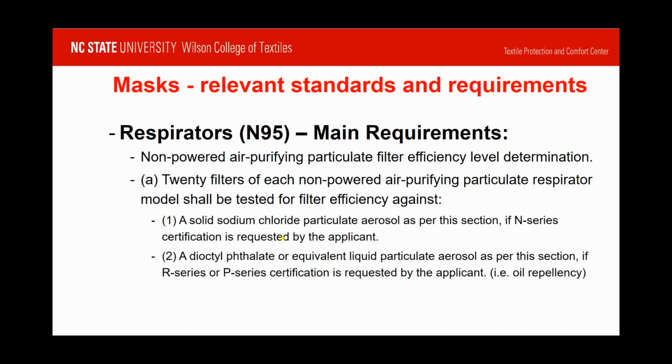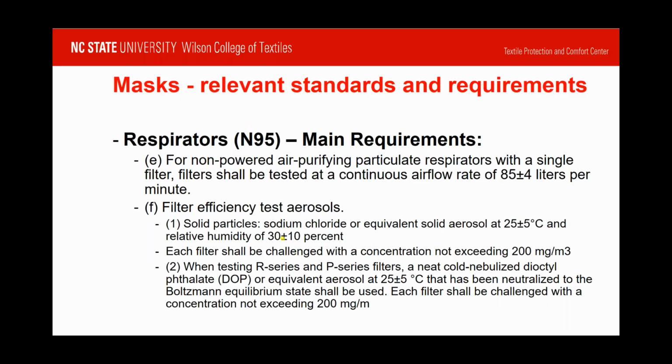The filters are tested. As you see here, 20 products are being evaluated for filter efficiency. A sodium chloride particulate test is done. The second one, the dioctyl phthalate test, is for the oil repellency characteristic. So that would only apply to the R and P series, the R95s and P95s. N95s only need to meet the first requirement of sodium chloride particulate filtration. Pretty much it's tested with a continuous airflow rate, and the filter efficiency has these requirements.